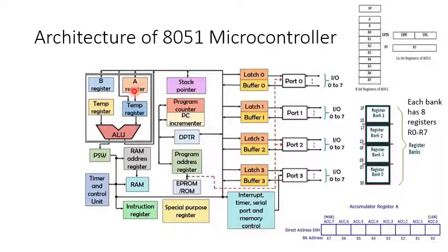Result of arithmetic and logical operations performed by the ALU is accumulated by the A register. Therefore, it is called the accumulator register. It is used to store 8-bit data and to hold one of the operands of the arithmetic logic unit during arithmetic and logical operations. Most of the instructions are carried out on accumulator data. It is the most versatile of the 2 CPU registers.